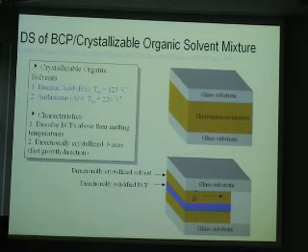So initially, benzoic acid is a solvent of the block polymer. So when benzoic acid crystallizes, the block polymers don't have the solvent, so they tend to phase separate. So since benzoic acid crystallizes directionally, the block polymer film also follows that direction, phase separates, and then self-assembles. That's the phenomenon we have: starting with a homogeneous liquid phase, it becomes directionally solidified into two different phases. This phenomenon is pretty much similar to the traditional directional solidification found in metal systems. That's why we put this name, directional solidification.